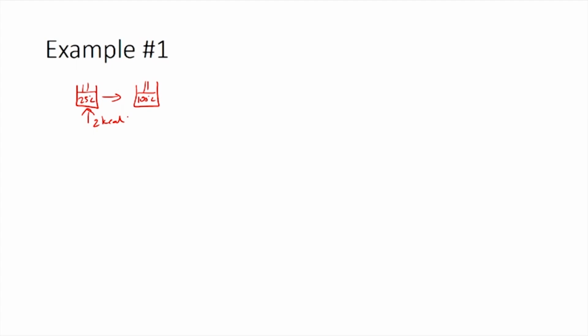We looked at the energy balance for a closed system as delta U plus delta Ek plus delta Ep equals Q minus W. For this process there is change in temperature, which means delta U cannot be 0. The system itself is not accelerating in any way, so kinetic energy will go to 0. We have been told that change in position of the piston can be ignored, but here there is no change in position of the piston anyway. So, potential energy will also be equal to 0.